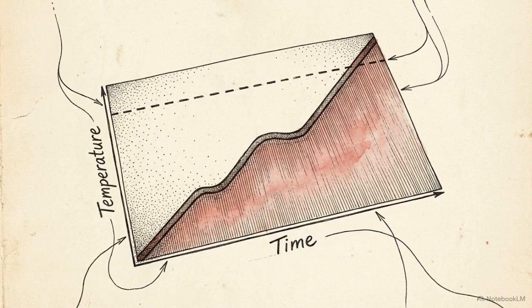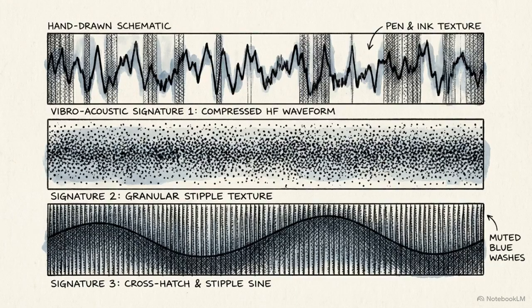For motors and power electronics, temperature monitoring is essential. Regression-based predictors track thermal trends to provide warnings of hotspot development and thermal runaway before severe physical deformation occurs. Acoustic and vibroacoustic sensing capture complementary, low-magnitude signatures. These high-frequency audio profiles detect early-stage mechanical damage when the fault is still microscopic.